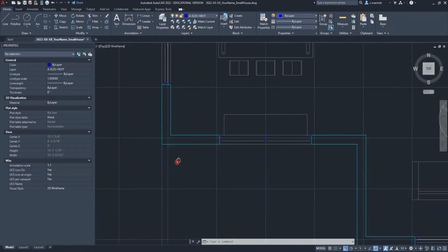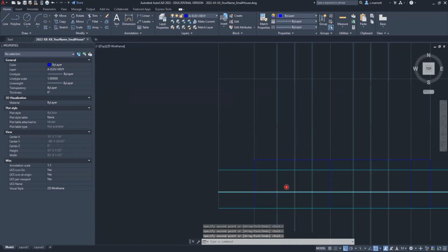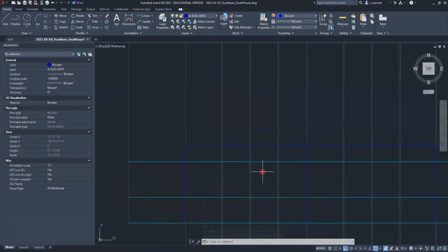All right, so now I can start copying these projection lines. So here we go. And I'll put them at every window frame and then the window opening. I'll do the same for this window. Just keep making copies. Copy, copy. Now I'm ready to draw these in. Before I do that though, I'm going to offset 1.5 for the top frame and for the bottom frame.